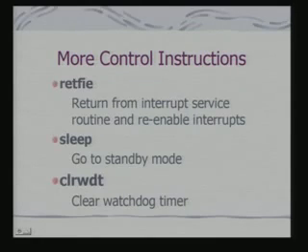Effectively nothing, because in both cases you need to get the return address from the stack. In case of PIC, you have a hardware stack, so the return address is stored in the hardware stack and you have to get it from there. But in this case, this instruction typically re-enables the interrupts.